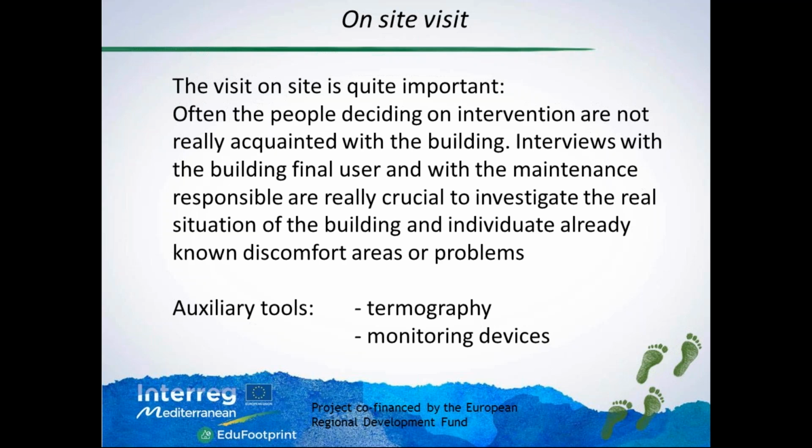On the on-site visit, it's a matter of dimensioning. So it's a check if the measures on the drawings are okay, how the elements of the building are, and what the status of the elements is, if the plaster is broken, or if there is some other refurbishment needed, or the plant: is it an old plant, a new plant, are there controlling thermovalves or something like this.